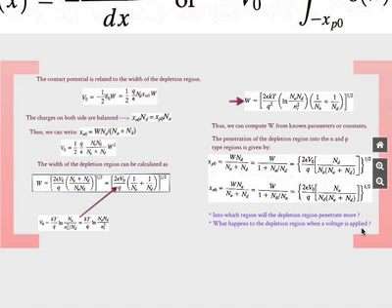What happens to the depletion region when voltage is applied? We briefly mentioned this. What happens is the bands bend. If it's forward biased, the depletion region gets smaller. And the way to think about this is you can look at this equation. Okay, this W is the total width of the depletion region. Forget everything else.